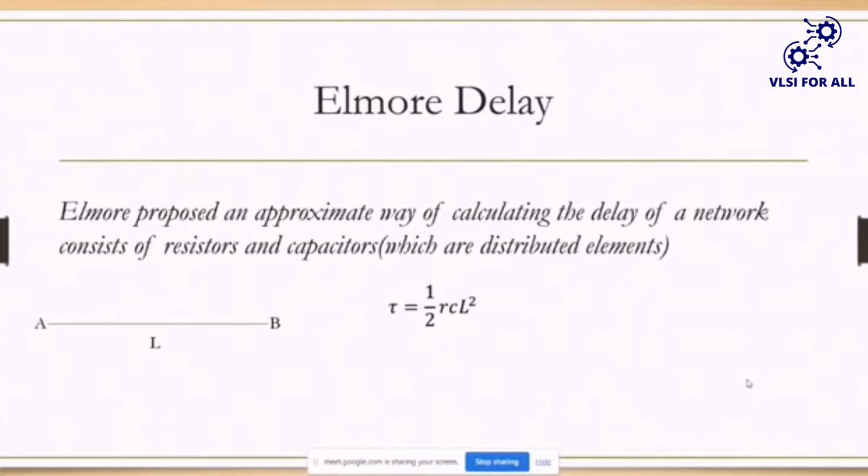So guys, from this you need to understand one point. By reducing the interconnect length, you can optimize the net delay. Remember, this is one of the optimization techniques that you will get in interviews. People may ask you, can you tell one delay optimization technique? As of now, we come across only one optimization technique, called buffer insertion.